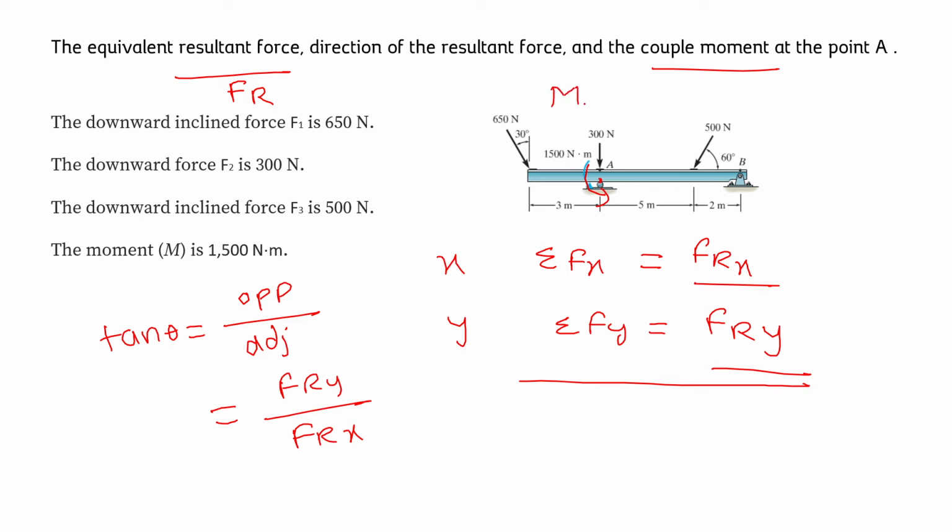to resultant force will be equal to summation of moment due to forces about point A. So with this help, we can also find the couple moment. So now let's begin. So as we discussed, there are two methods in order to calculate the moment.